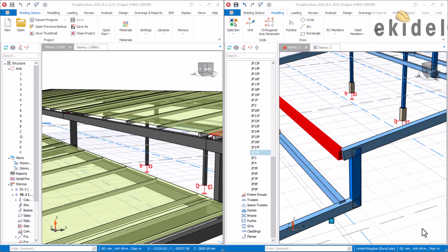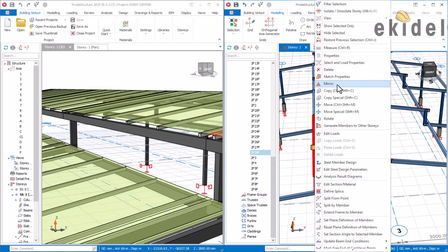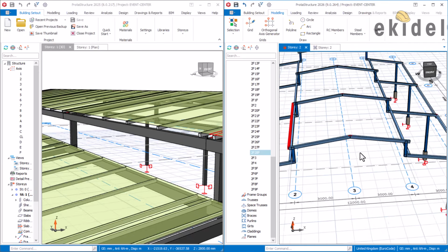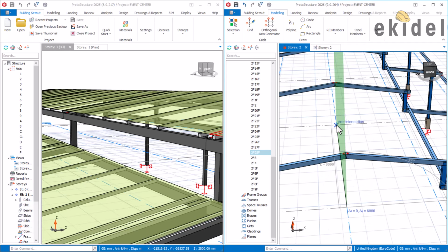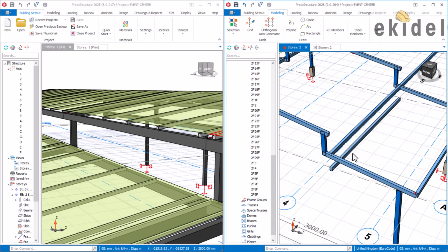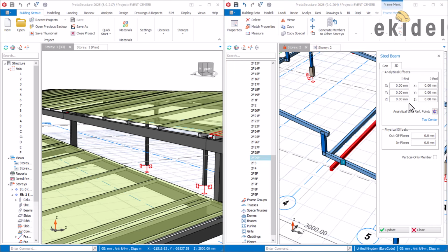Correct. So that's okay. So we come now and then mirror this on the other side by clicking on this. Right click here and then say mirror, and then we mirror from this point. Make sure you are at that point. Click here too and then say copy, and that will be found here. Then come again here and change the value again. Right click here, property of it, and type again the same value that we used, 1.5 by 1.5, and then enter that value, and that will be correct.